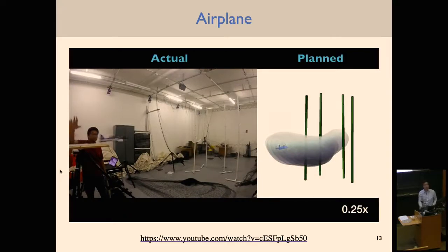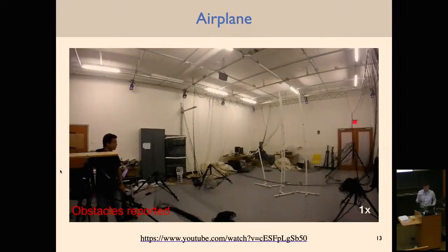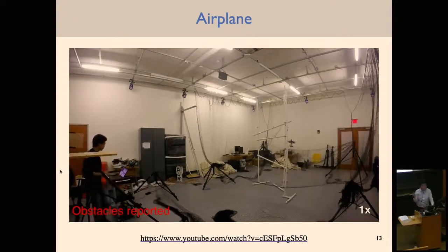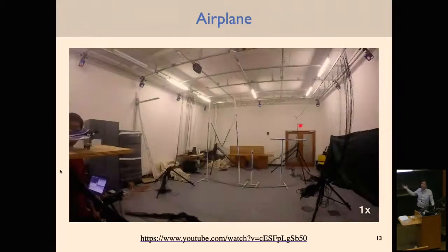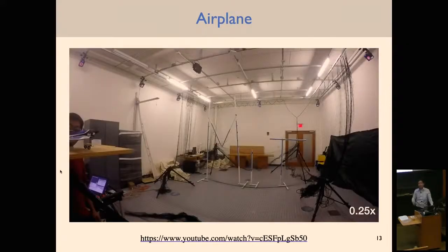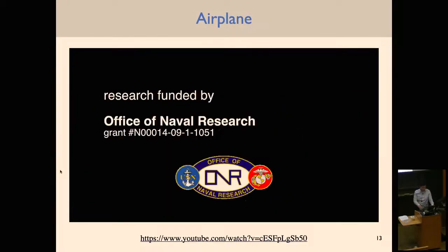These are different clips showing the different trajectories that are found with the associated tubes that the system is guaranteed to remain in if it applies the feedback controller. The basic architecture here is identical to what I described. You plan a bunch of trajectories, and then you have associated feedback controllers, using exactly time-varying LQR for this system. And then I was bored one day, and I was at MIT, so I made the obstacles spell MIT, which I regret now every time I show that video.